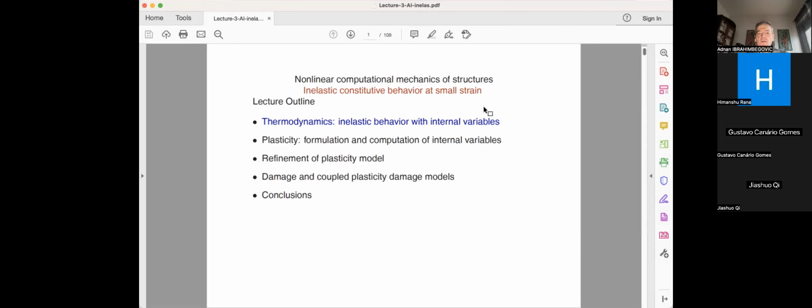There's something called the damage model, and that model is there to take into account change of the elastic properties. Rather than taking irreversible plastic deformation as internal variable, this one takes something called damage compliance. Damage compliance is, to start with, the inverse of the elastic modulus in the 1D case, and then can go bigger and bigger as you get more cracks. And then what we managed to do is contrary to many other early works on damage in the style of Kachanov, especially typical of the French school, with Jean Lemaitre and collaborators.